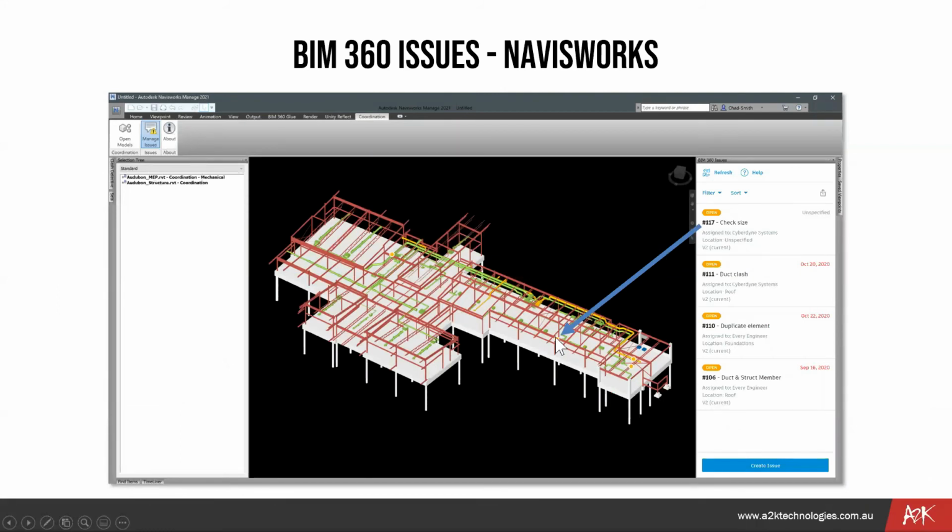They've obviously been aggregated, and within this aggregated model, we can now start seeing, by way of these little orange pins, where the issues have previously been raised. The Issues tab, which is open here on the right-hand side, is now drawing in issues that have been raised over inside of BIM 360. It's important to note that the issues that it's pulling through now are only those issues that were attached to these opened models. So we're getting some context on the issues so that we don't get the full list, we're getting a filtered version of that list instead.